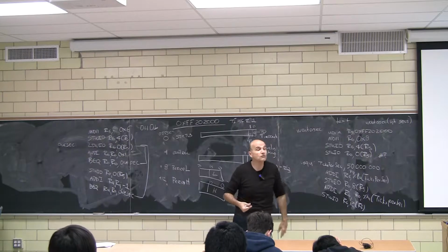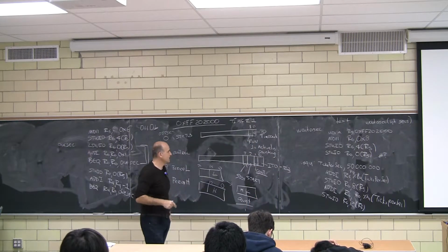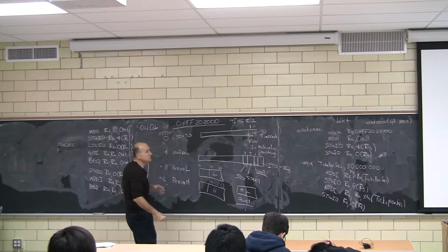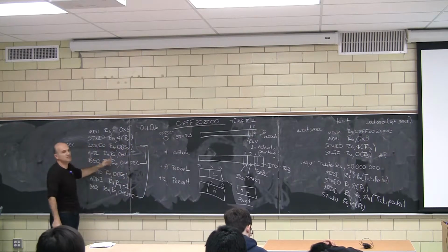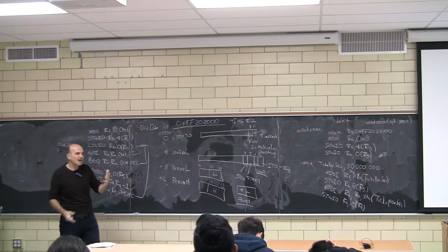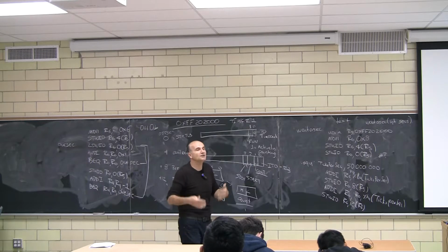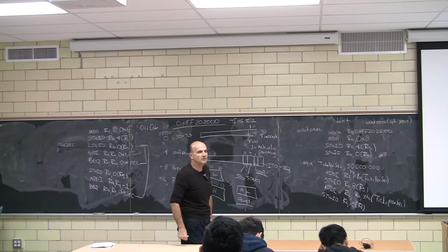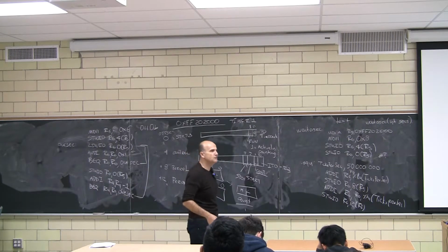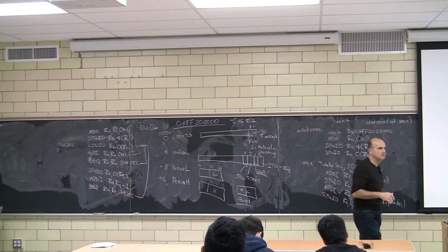That's why you use continuous. If you haven't done that, there's going to be some, I think the right term for that is jitter. That is, an event has happened, but you take time to respond to it. That is variable time. Fine, it's not that much, but it's still something. So you're going to count time with some, what's the right term? It's not going to be accurate enough. Depending on the application, that may be an issue. If you're doing audio, maybe not so much because this is megahertz. If you're doing video signals, obviously, you're going to see problems in your screen.